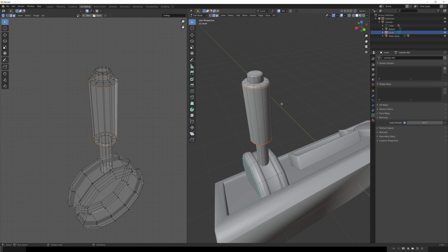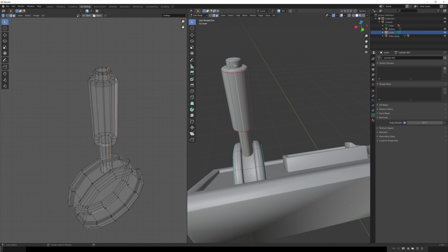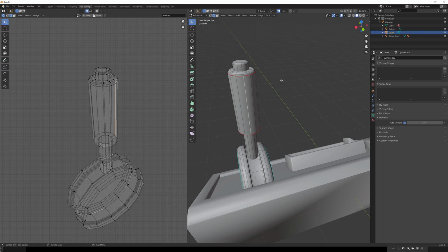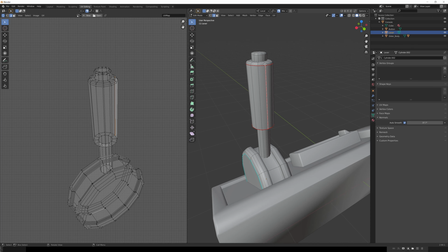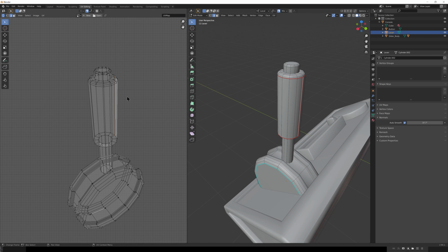If I want to flatten this thing on circular objects, finding the cylinder part, making cuts at the top and the bottom, and then adding one that goes down the side, like right here, is usually the best way, because if you think about it interactively, this part and this part are going to rip off, and then they're going to flatten out into just a roll, almost like if you took a roll of toilet paper, right? The cardboard piece, and split it in half and just unrolled it outwards. This is going to come out okay.